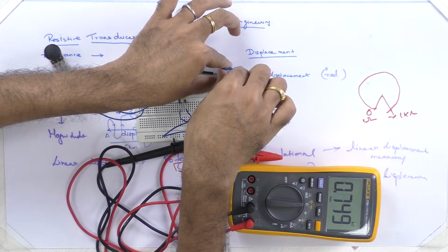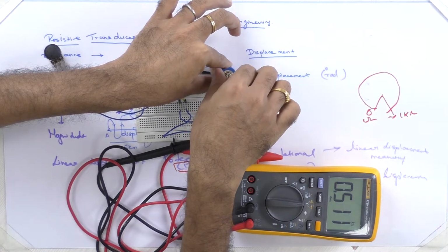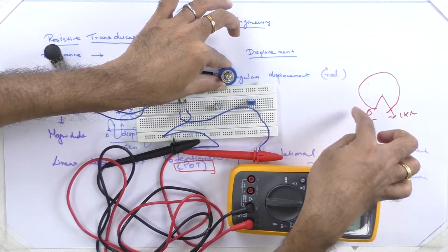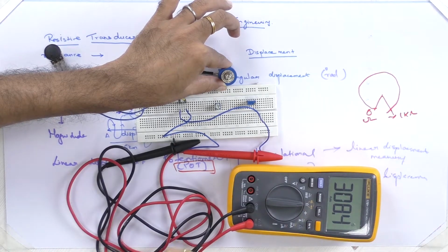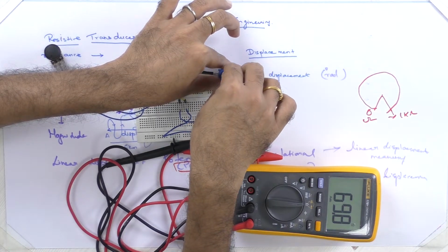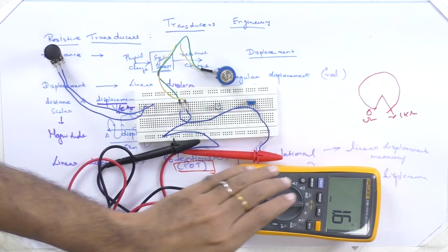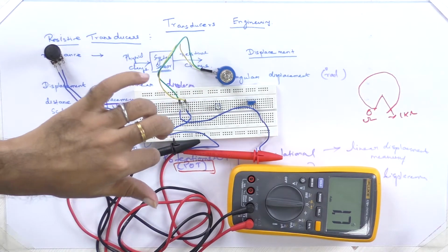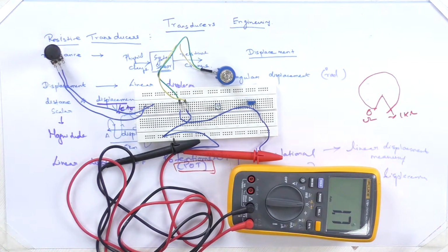Okay, for very precise measurements we can use this for fine tuning and also for finding the displacement, that is angular displacement, that is happening in a very precise manner. We can use this kind of potentiometers. This is a helical potentiometer, as I explained to you. This is a helical potentiometer, this is a normal rotational potentiometer. Inside it has many windings. Here you saw many windings in a translational part. Like that, inside it will have many windings, so that you get this kind of effect.